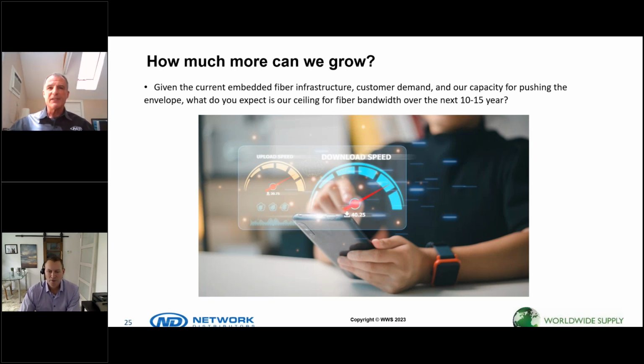So the first thing you ask yourself is, well, what brand are you using? If it's Adtran, we know, or DZS, we know that they're using SFP pluses. If it's Nokia, and soon to be Calix, it's going to be SFP DD. So the first thing is brand, what client cards they have, and what the platforms are. We offer both the SFP plus and SFP DD optics. We get them from several of the large suppliers that actually service many of the OEMs already. So we know that we have the hardware available. What's key is getting them qualified within the latest versions of the line card and the system with the OEMs.